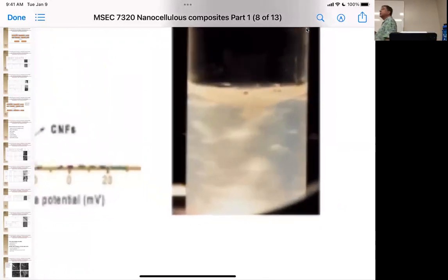And then turbidity here. Turbidity gives us an idea about large and small particles. Large particles will scatter light. After your particle gets smaller than about 1/6 of the wavelength of light, it no longer scatters. So you can actually say that there are lots of large particles in here. As your solutions get less and less turbid, or more transmissive, you have to hit it with a laser to watch it scatter. But that lower color is telling you there are fewer large particles scattering. So turbidity is a really good measure of how far along your process is going.